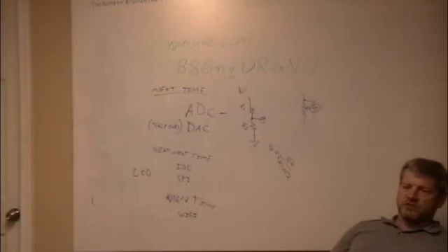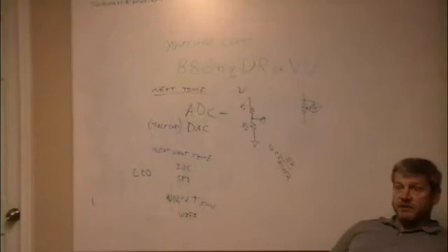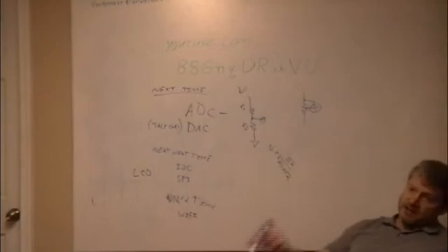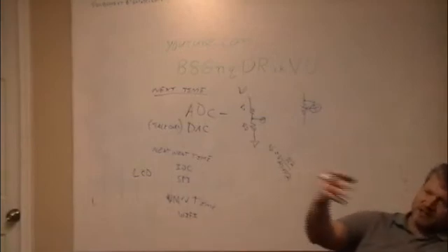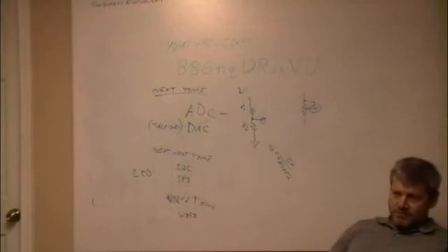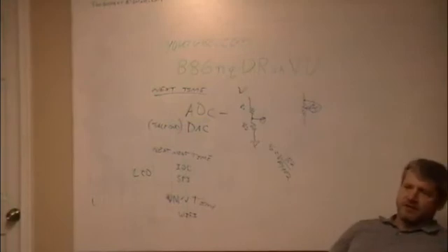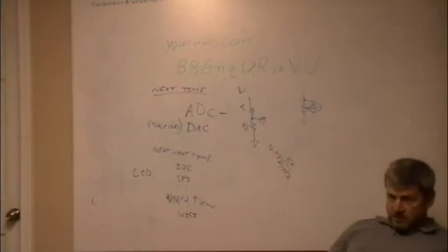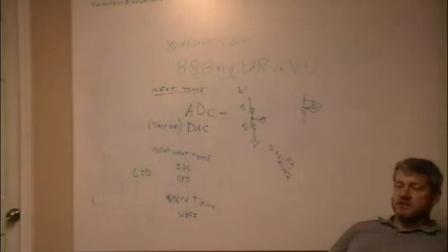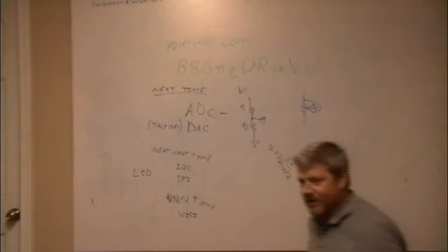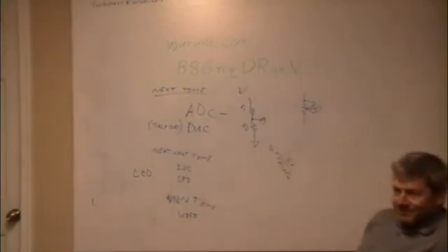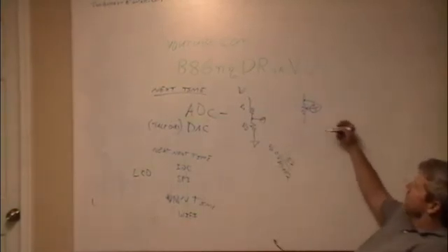Most of the thermistors are wrapped in epoxy, and it'll outgas into your process, and it can screw up your process. And vice versa, that epoxy cures at about the same temperature as what you're doing, and your epoxy process can then screw up the thermistor, and then it might not be any good after the next process, and you have to change it out. Thermocouples, when you buy that kind, are almost always encased in stainless steel. And then we wrap them in flash tape to put them next to the laminate. So they're effectively sealed from the product.